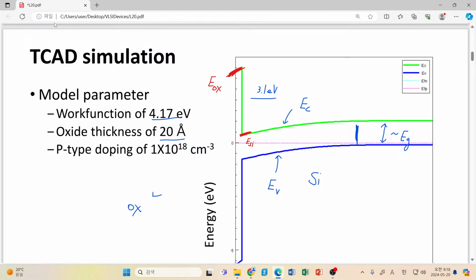So this is corresponding to the difference of their permittivity. You know, this one has just 3.9 of vacuum permittivity, and this one is almost 3 times higher than that in the case of silicon.